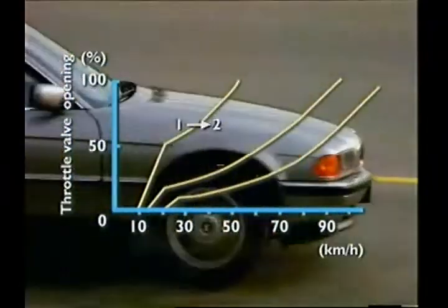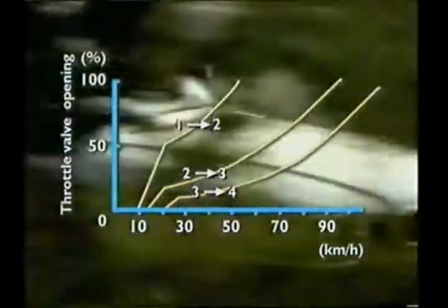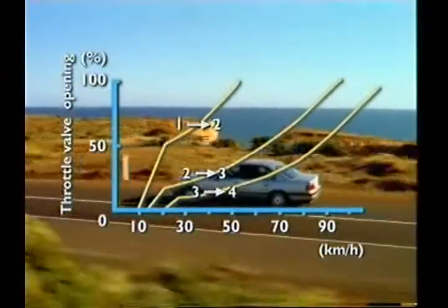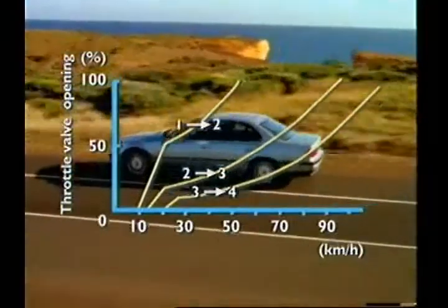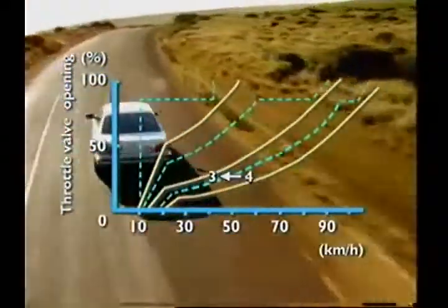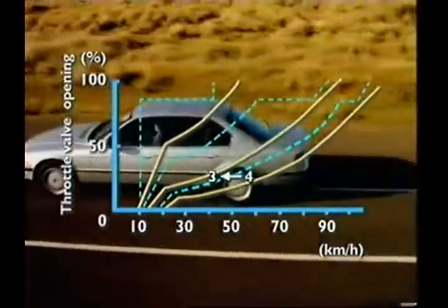In order to slow the vehicle, the driver lifts his or her foot off the accelerator and, if necessary, applies the brakes. In normal driving, closing the throttle prompts the transmission to upshift to a higher ratio if it is not already in top gear. In a higher gear, the engine contributes less to the braking process. And when the accelerator is depressed again, a downshift usually takes place.